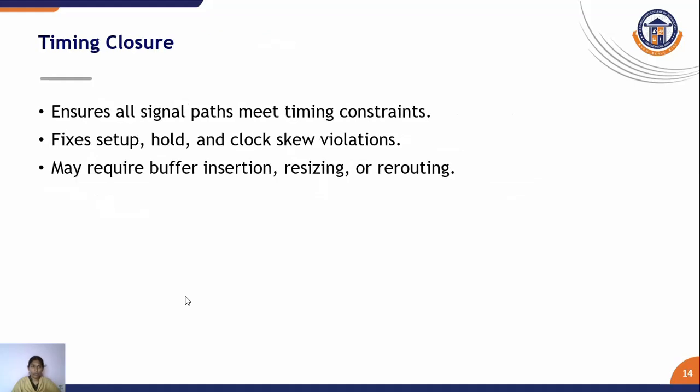Once we complete routing, next we check the timing closure. Here we ensure all signal paths meet the timing constraints or not. Here we fix the setup time, hold time, and clock skew violations. It may require buffer insertion, resizing, or rerouting.